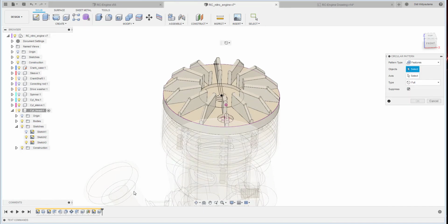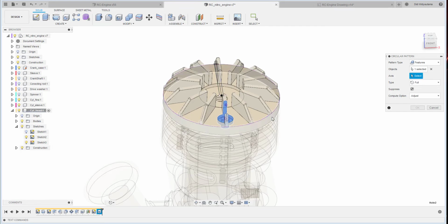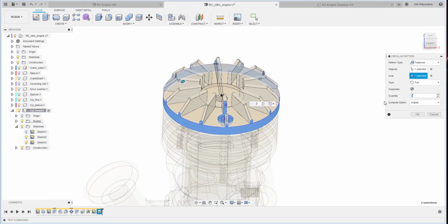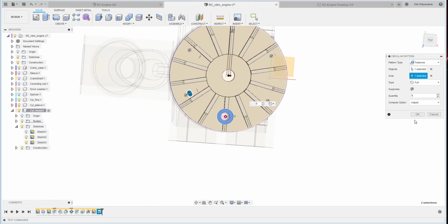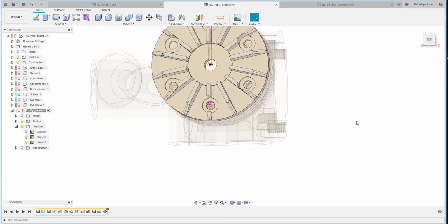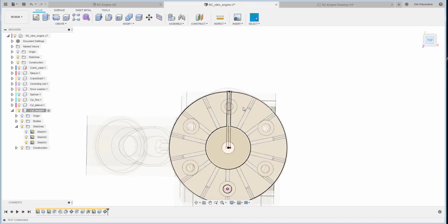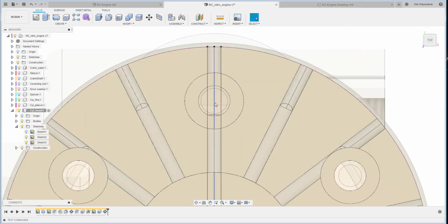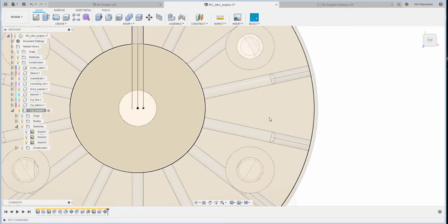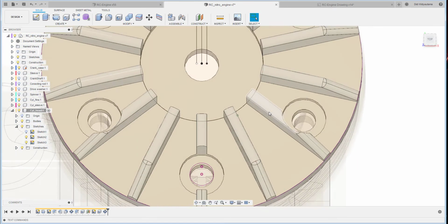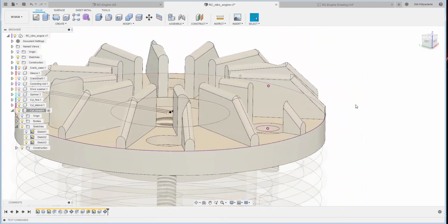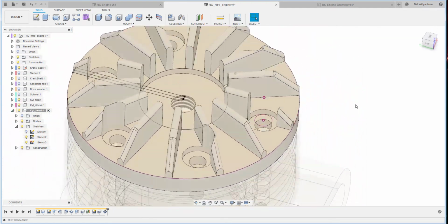and I create a circular pattern with the feature. The axis will be over there, and 6 is the number of instances. Okay, let me check for the hole one by one. Okay, yeah, okay, I think it's all done for this hole.